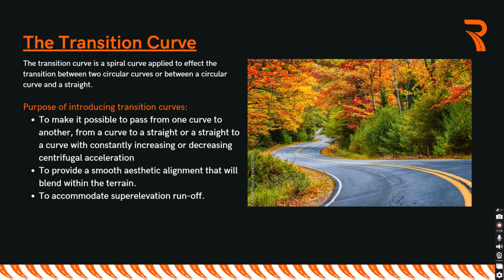As you move, the vehicle or the driver will not necessarily be having a constant or stable acceleration. It will be increasing or decreasing, and that is why we need the transition curves. Of course, there are instances where you don't need transition curves, mostly when the radius of the curve is so big that the forces are cancelling out.